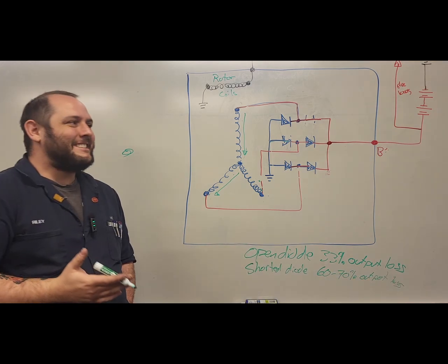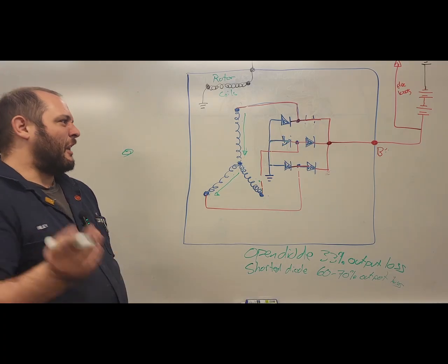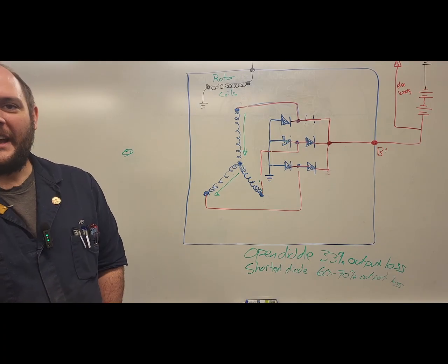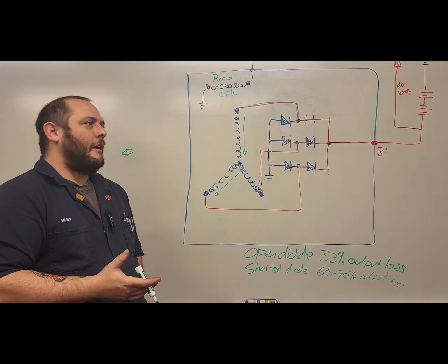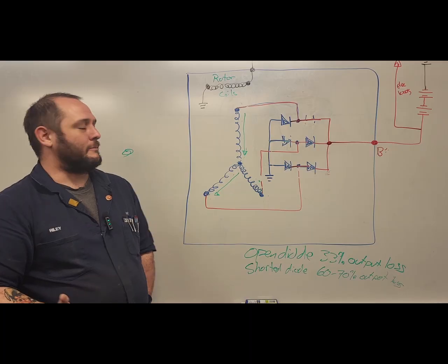That output loss is when we do an alternator maximum output test. So if I have a running piece of equipment, I load up that system, I'm looking for how many amps that alternator is capable of putting out. That's the loss I'm talking about.